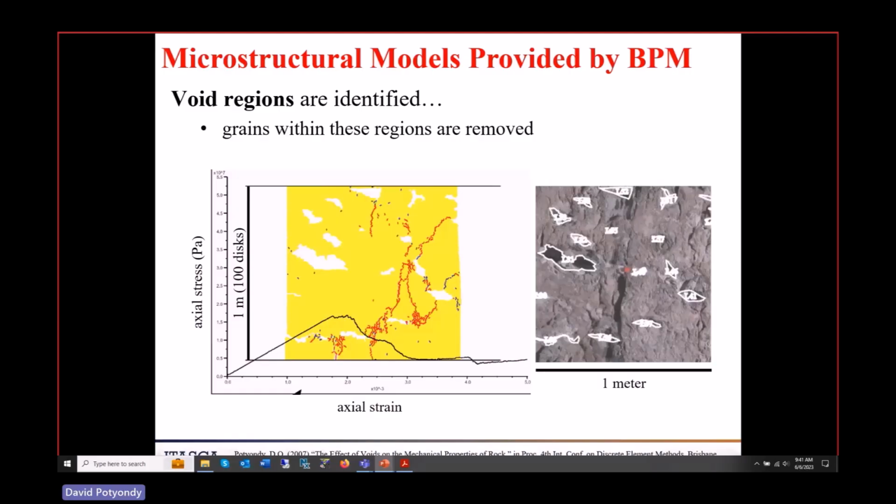Okay. So for that work, they needed to do all kinds of modeling. They needed to do continuum models because they needed to do big, large regions of the tunnel. But they needed to get some idea of how all these voids in the system affect, for example, the UCS and the modulus. And most of the cores they took, they were not able to take big enough cores to test the effect of these voids. So they resorted to doing these PFC 2D models.